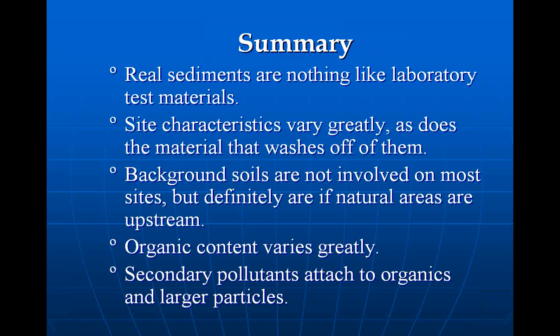It's a different thing, and we try to fight erosion all the time. And erosion is what will give you your background soils. It's a little silly to base all your designs on background soils, but there's several states that do it, and it just doesn't make a lot of sense. Now, it does make sense if you're in Savannah, Georgia, on the beach, or Destin, Florida, or Virginia Beach, Virginia, to look at your background soil and the distribution of the material that's going to be tracked onto your site, that sort of thing. Organic content, it's amazing how much it varies.